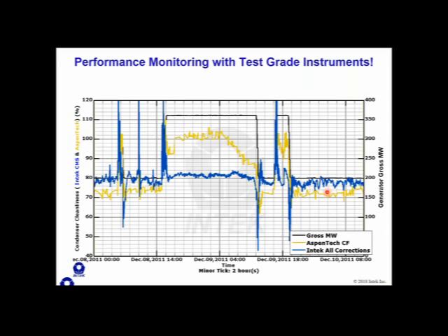Here's what I want to say. I chose this case study for two reasons. Number one, always validate the data before troubleshooting. And number two, have faith in the formulas. The formulas are actually really good. The HEI formulas are really good for monitoring performance, even in changing conditions such as inlet temperature and load changes. They do work quite well.